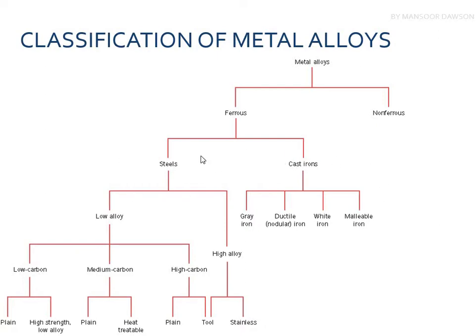In steels, you studied the iron carbon diagram, in which from 0.3 or 0.2% carbon up till 1.8 or sometimes 2% of carbon is there, and after 2% of carbon there is no more steel. The carbon percentage from 2% to 6% almost is cast iron.